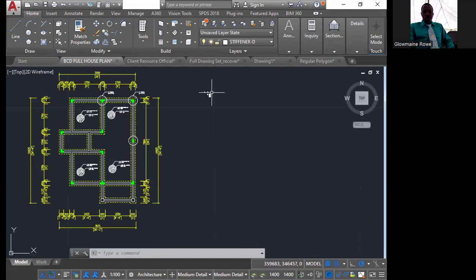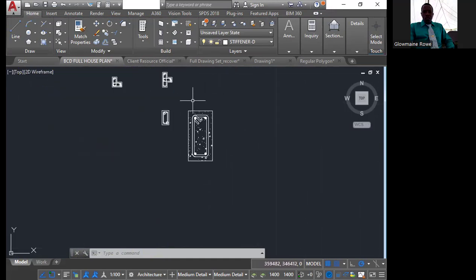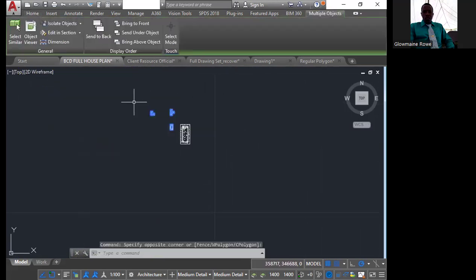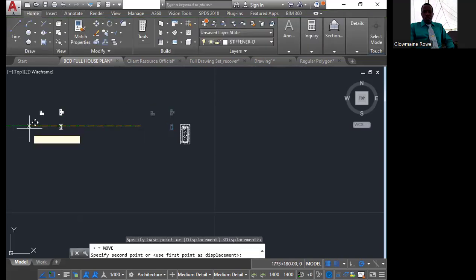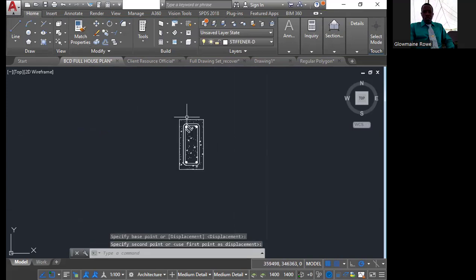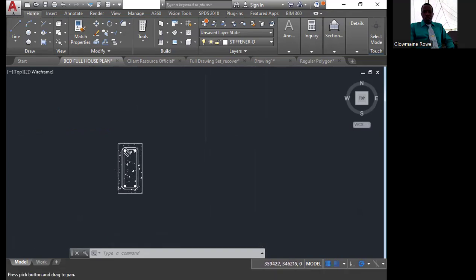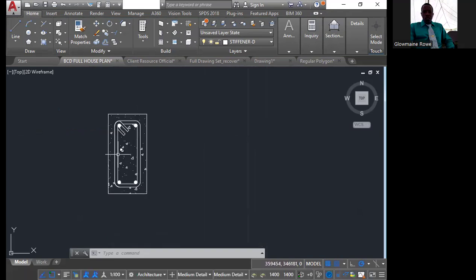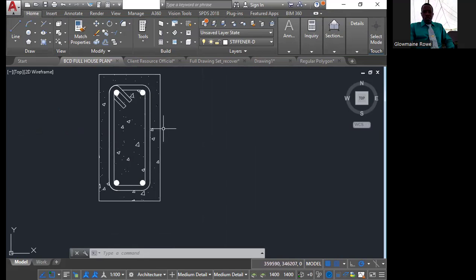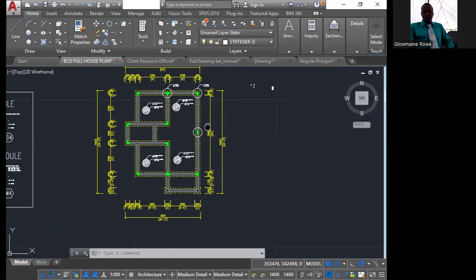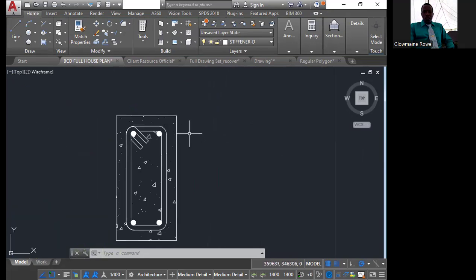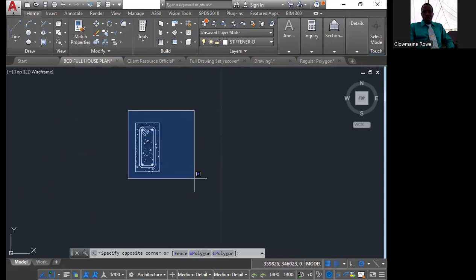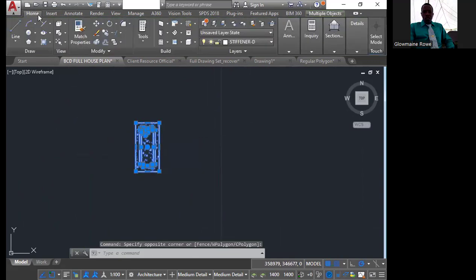But when you have your stiffener, because they're so small, you will have to use a scale that makes them larger. So we can use a scale of about 1 in 10 or 1 in 15. In this case, we can probably use 1 in 10 because this joint is small, so it won't take up that much space on your page. So 50 divided by 10 is 5, so we can scale this up by 5, and then it becomes scale 1 to 10.